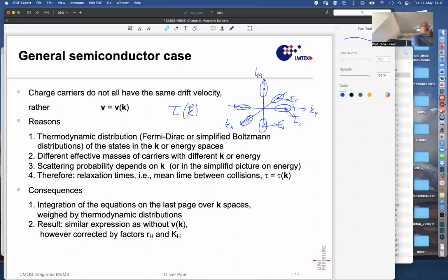The other one is the lattice scattering. Lattice scattering is caused by the motion of the silicon lattice, the motion of the silicon atoms in thermal vibrational motion. Those atoms vibrate, and this imperfect crystal is also an inhibitor against free motion of the electrons. And both have different thermal behaviors.